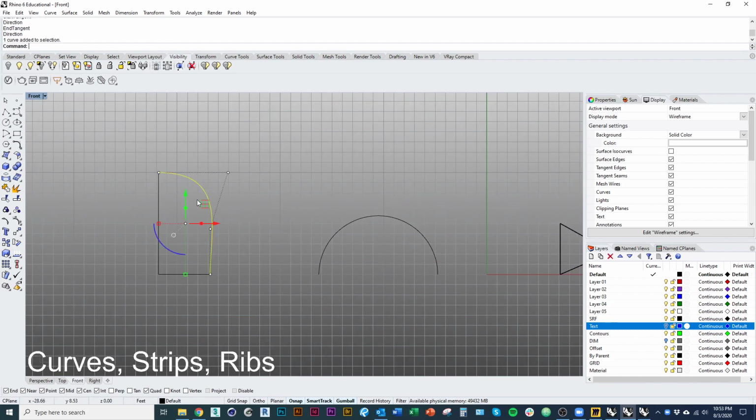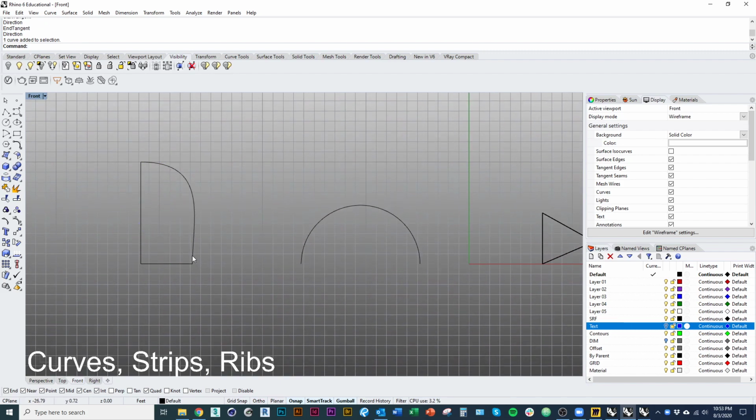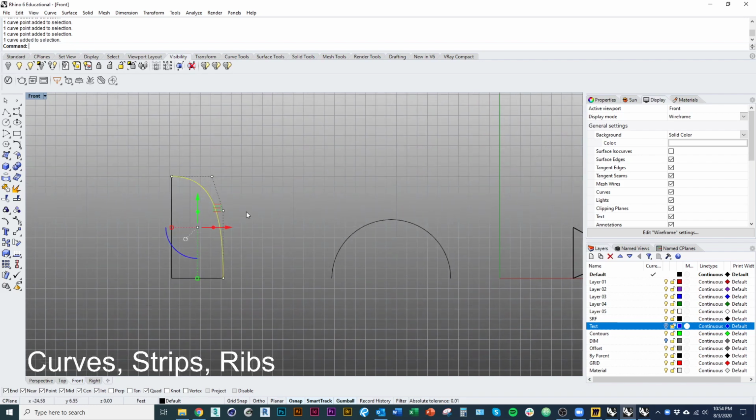I guess it doesn't. So what you can always do, you'll notice that when you've drawn a curve like this, where the end and the beginning are defined by a tangent, the control point directly adjacent to that curve, once you've drawn it, is always in line. It's like aligned with that tangent, right? So basically, in order to change how strong those tangents are, we just move these points in the same direction with the original direction or tangent of the curve at that point. So we can kind of edit the geometry a little bit that way once we've drawn it.